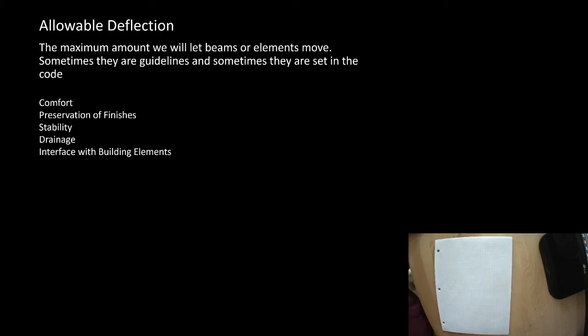Okay. Before we dig in, I just want to remind you about deflection criteria. So there's the maximum amounts we'll let beams or elements move. Sometimes they're guidelines and sometimes they are set in stone in the code. The idea here is about comfort and preservation of finishes.